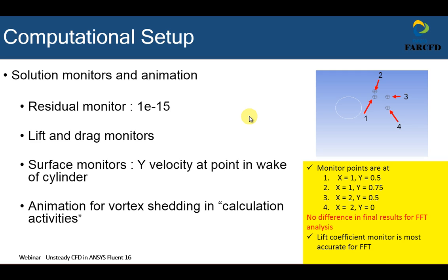Please observe the transient behavior of the monitors as well as their average, minimum and maximum values. We will use the animation panel in calculation activities to make the animation for the vortex shedding. At the moment maybe you do not know how this is done in Fluent, but do not worry, we will show you all steps done in Fluent in part 2 of this webinar.